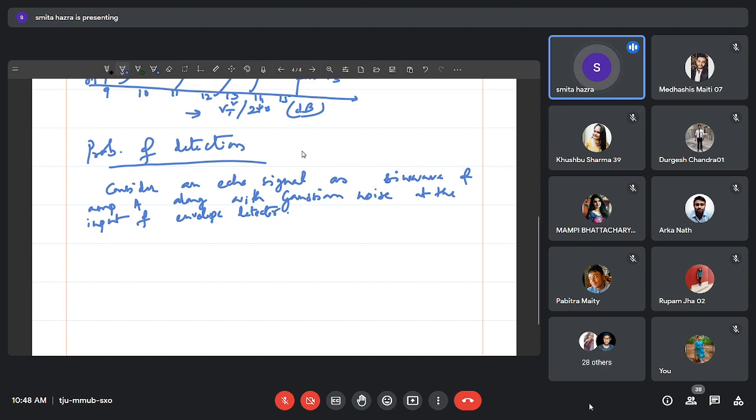Usually the entire receiver chain is very long, because prior to the IF amplifier the matched filter is there, prior to that a low noise amplifier is there, and a one-stage mixer circuit is there. But we are not taking the entire chain, because the calculations would be much more complicated. So let us consider only the crucial part, from where we take the voltage trace or phase trace of the received signal.